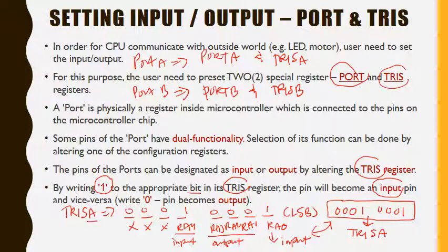But what is the use of the PORT register over here? PORTA register, what is the use of this register? In PIC, this PORTA register, we are talking about the register now, is where we can read or write the current value to the pin.